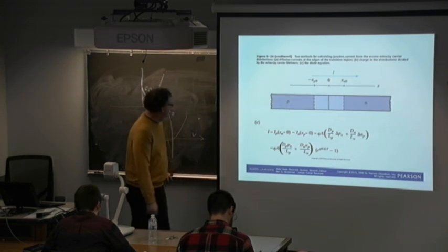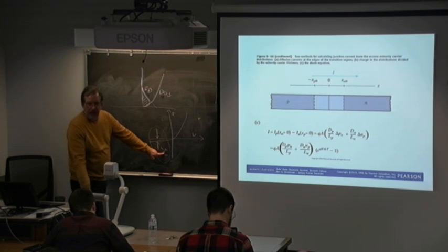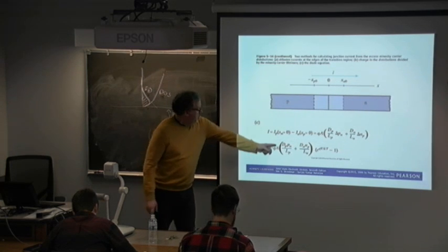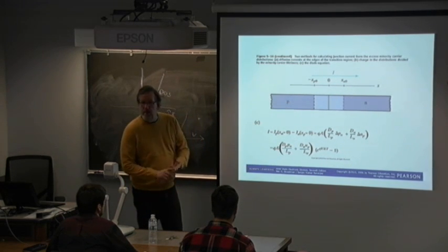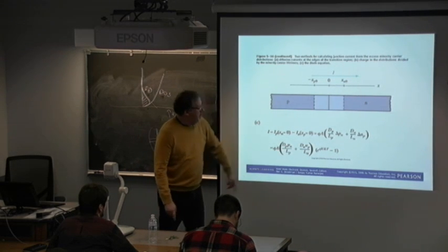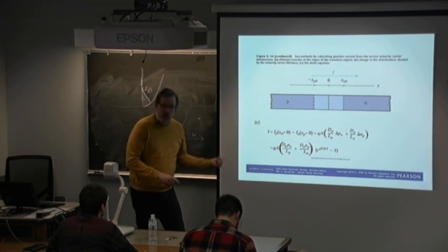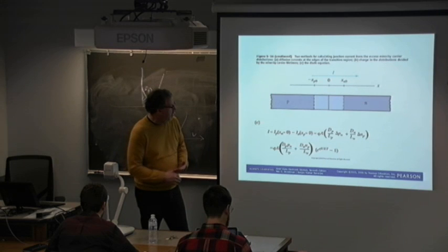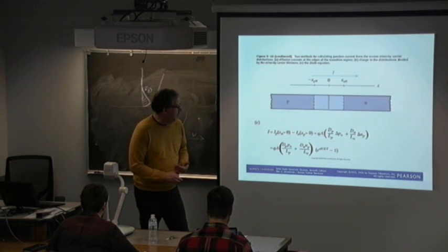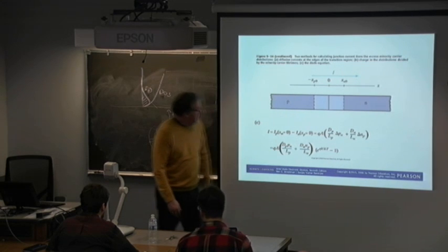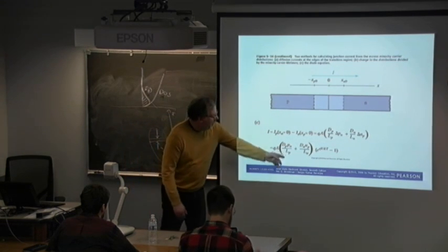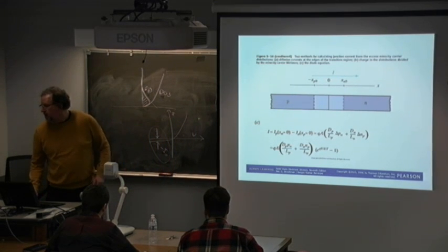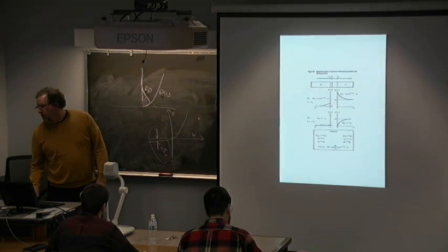So I can actually figure out what my reverse saturation current, or minus I naught, should be based on foreknowledge of the material parameters, because diffusion terms can probably be determined by the doping density. If I know what I doped it with, the majority carrier, I can certainly calculate the minority carrier knowing the intrinsic carrier concentration. And intrinsic carrier concentration is just a material parameter. Diffusion length is dependent upon the doping level. I can figure that one out or even measure it. So all of those are things I can measure or ascertain from first principles.